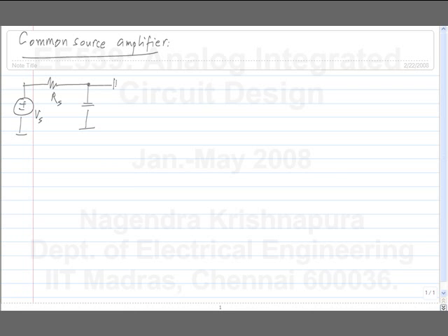The transistor is modeled by the transconductance and the three parasitic capacitances between every pair of terminals. This is CdB, and we have the output conductance of the transistor and any load that you connect to the output of the amplifier. So any explicit capacitive load you connect can be absorbed into CdB also.